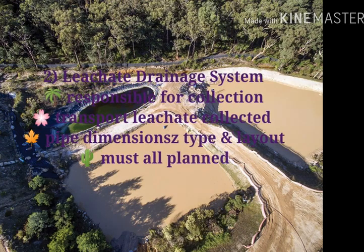Leachate drainage system. The leachate drainage system is responsible for the collection and transport of the leachate collected inside the liner. The pipe dimensions, type, and layout must all be planned with the weight and pressure of waste and transport vehicles in mind. The pipes are located on the floor of the cell, and above the network lies an enormous amount of weight and pressure. To support this, the pipes can either be flexible or rigid, but the joints to connect the pipes yield better results if the connections are flexible.